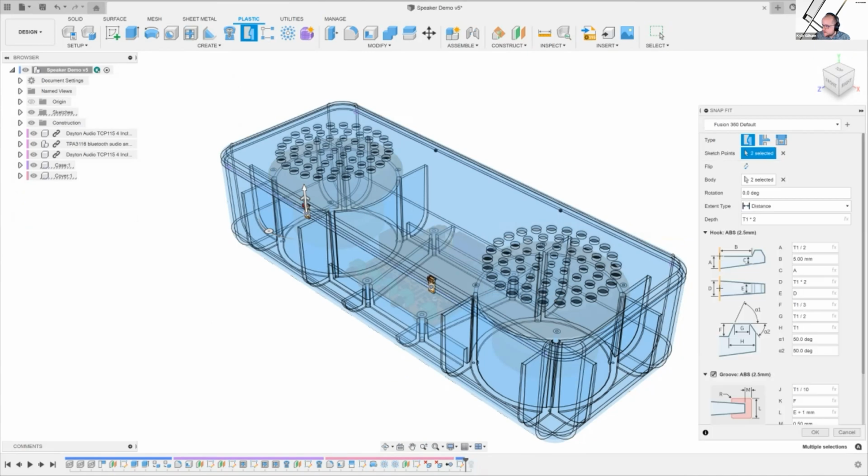I'm going to go ahead and click these two. And again, similarly to the boss command, see how everything is controlled and created in this dialog box. All of these here, you can see that the thicknesses, a lot of the diameters are already preset for you. A lot of this is driven by how you set up your materials and your standards at the beginning. And we're not going to go through that here. We'll probably have some other webinars that go into more detail, but it's really doing that manufacturing thinking ahead of time. So it drives, like I said, into these features downstream that you're working on now.